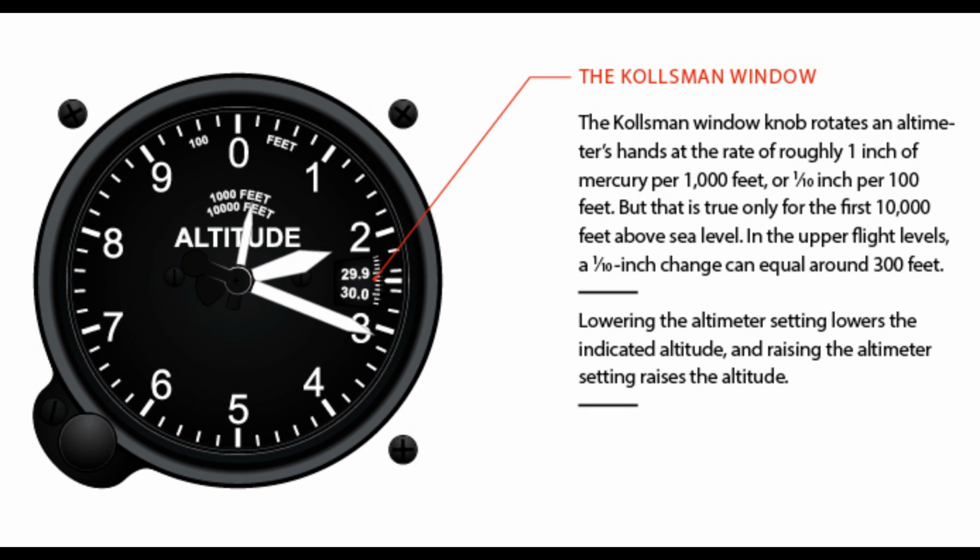Barometric pressure for local altimeter setting, QNH. A local altimeter setting equivalent to the barometric pressure measured at an airport altimeter datum and corrected to sea level pressure. At the airport altimeter datum, an altimeter set to QNH indicates airport elevation above mean sea level, MSL. Altimeters are set to QNH while operating at and below the transition altitude and below the transition level.